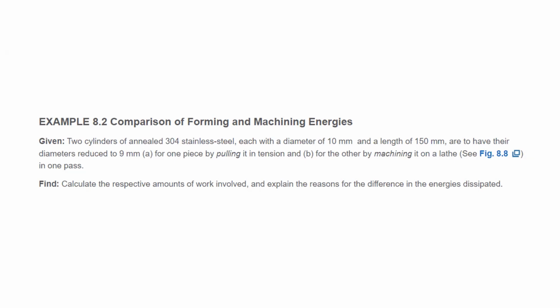So this K and N is related to the strain energy, the power of the strain energy, the equation of the strain energy. So this is U, right? U equals the integral of sigma, where sigma is K epsilon to the N, so U equals K epsilon to the N plus 1 over N plus 1.